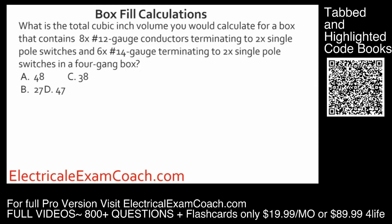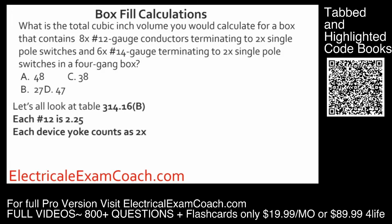What is the total cubic inch volume you would calculate for a box that contains 8 12-gauge conductors terminating to 2 single pole switches, and 6 14-gauge conductors terminating to 2 single pole switches in a 4-gang switch box? This looks like a tough question, but I know that you can do it. First, we're going to head to our table so we can get our values. We know what each 12 is, and we know that each device yoke counts as 2 based off the largest wire that's terminating to the device.